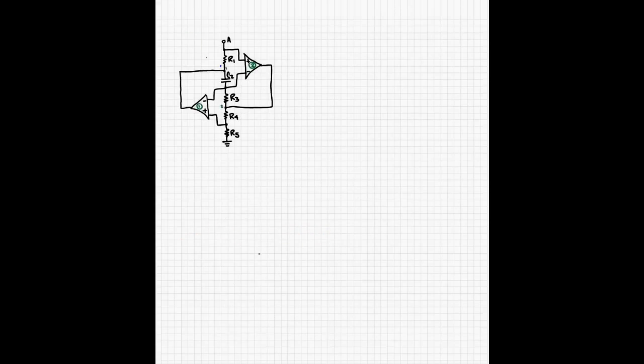Okay, so that's nice. Now, we want to see what happens to the circuit as we increase the frequency. Okay, so let's just write that really quick. So C2 capacitor will start acting as a short. So that means that we can replace it in the circuit. So I'm going to erase it out of there and put a wire.